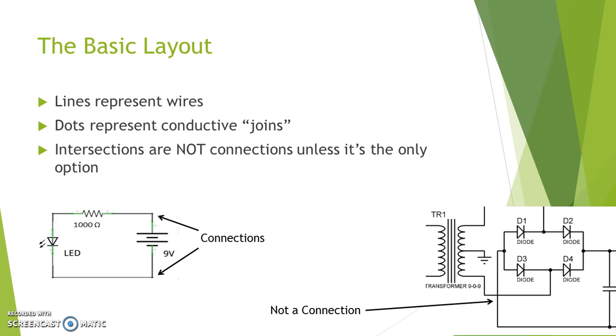Sometimes you'll see a little, almost like a U that shows a ramp going one wire over the other, but it's often not convenient to do that. And so we have to be able to interpret this piece. So we can see there are lots of places where we do have intersections of more than two wires, and there's a dot to tell us that this is a soldered joint. And in this case, no dot means this wire goes over top of this wire without them connecting. I hope that's clear.